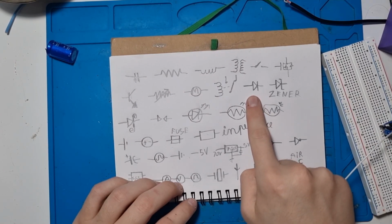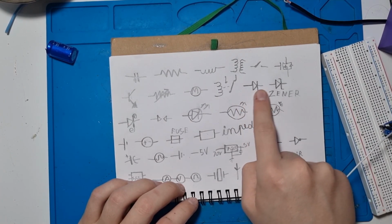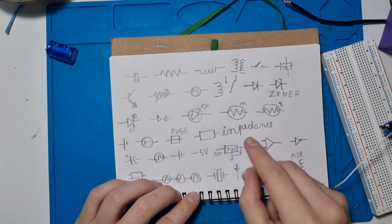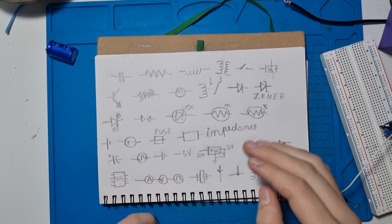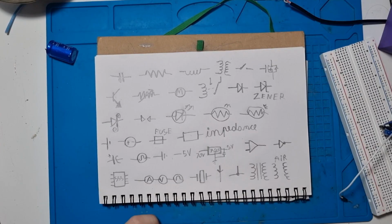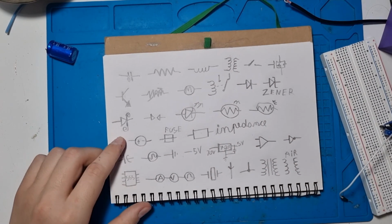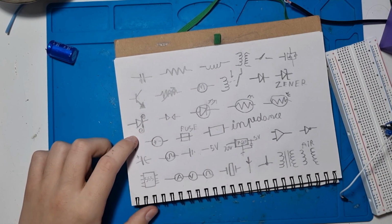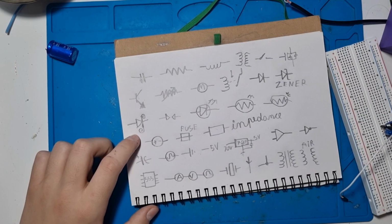Now, this is a regular diode. This allows current to flow only in one direction. This is a Zener diode, and this can be used for limiting voltages or just making a simple voltage converter to get a lower voltage. Now, this is a Schottky diode. The schematic is simpler than what I draw here, but I recommend whenever drawing schematics, draw a Schottky diode like this. People will still understand it as a Schottky diode, but you won't confuse it with the Zener.